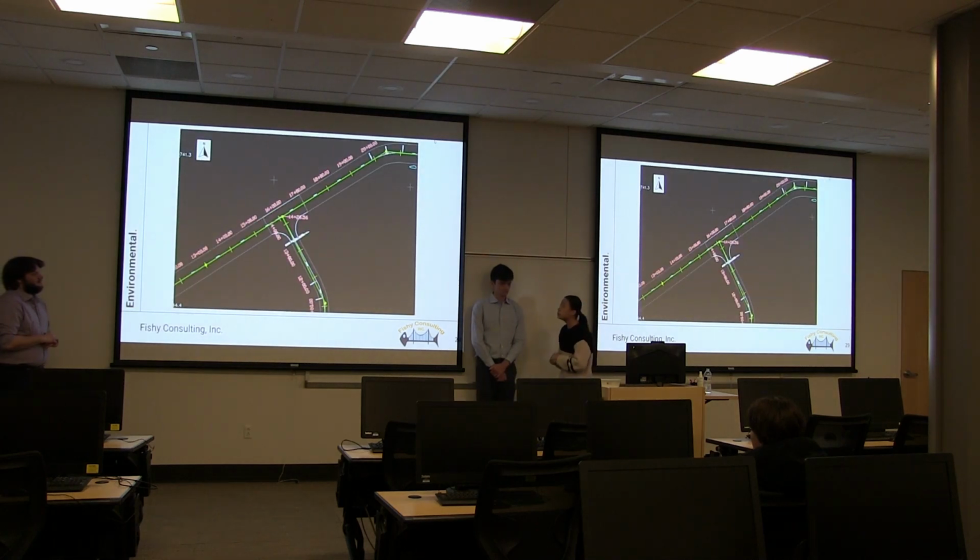This is a blown up view of the intersection. Note that this structure is a little more special than the other ones because it will be connecting both pipe networks to make it one. This structure has 3 connections in it, and the flow should be flowing west towards that lift station.